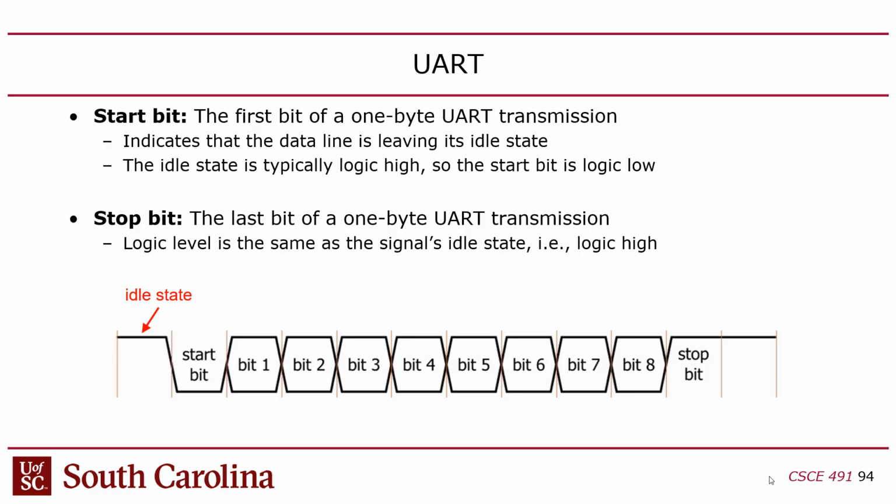And then you send bits, and then when you're done, you put a stop bit in, which is where you put the signal up for 1 bit time. Each bit is held for 1 bit time. Now here's the other problem with UART. The number of bits that you send for the data is also not fixed. It has to be pre-agreed upon. It's called the data bits. And the stop bits are also not fixed.